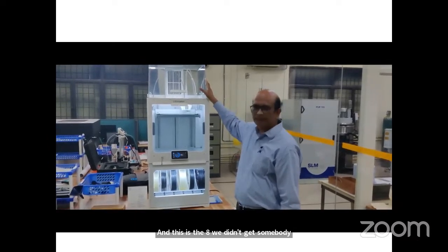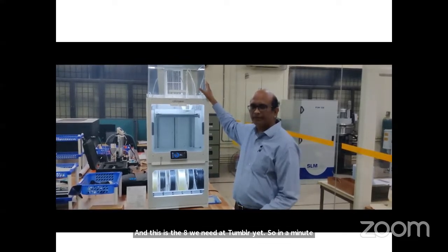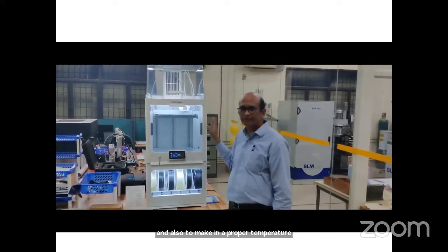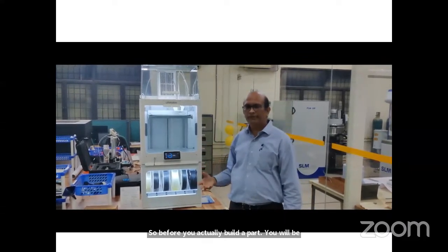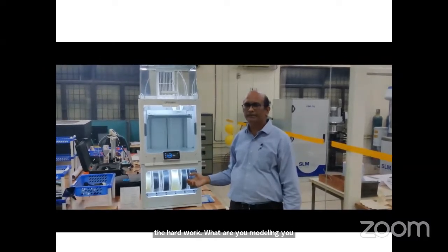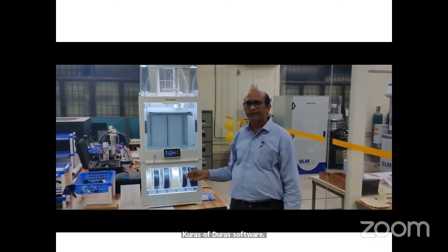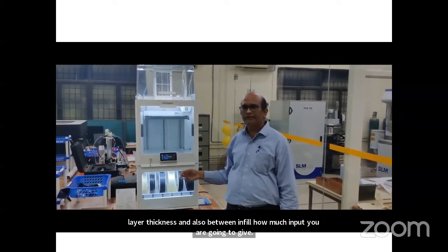In the air manager chamber you remove any moisture content, and also maintain the proper temperature inside. This works on software called Cura. Before you actually build the part, you model in CAD and convert it into an STL file, then import it into the Cura software, where you set up parameters like the layer thickness, how much infill you are going to give, what the raft is, and all those parameters.